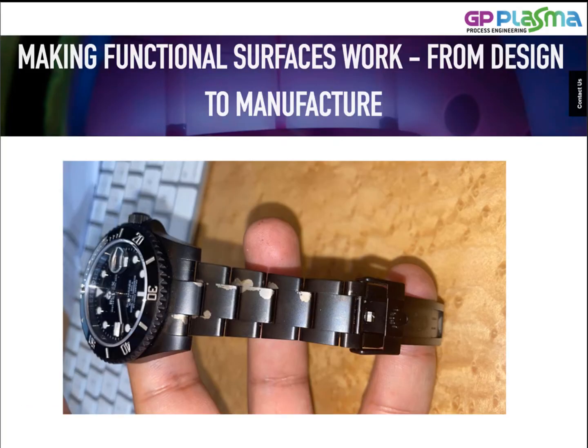Why do coatings fail? How, where, and under what conditions do they fail? How quickly can you fix it is the typical question. Where should you measure? What properties are important? With micro and nano indentation, you can obtain the information needed to answer some of these questions, but can you trust the 1/10 penetration depth rule for thin films? Instrumented scratch testing can also provide valuable information, but are you really measuring adhesion with it?